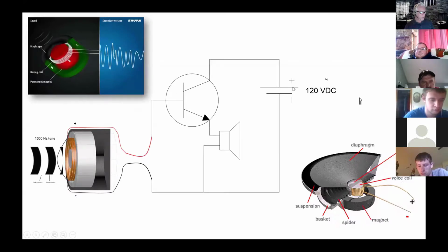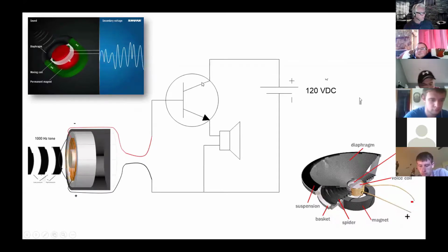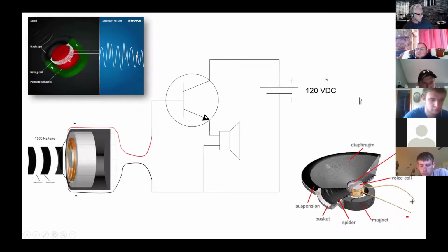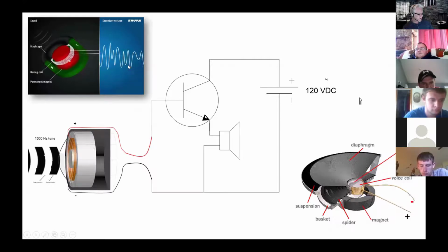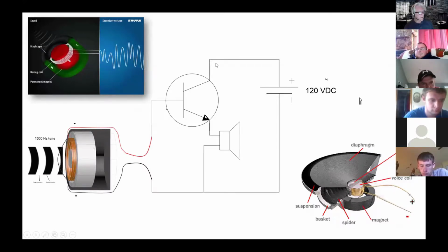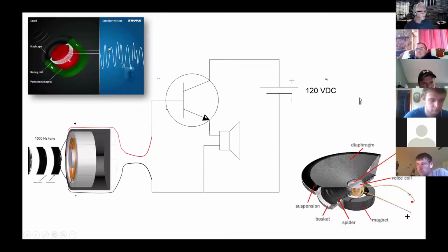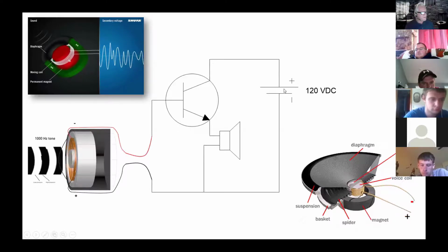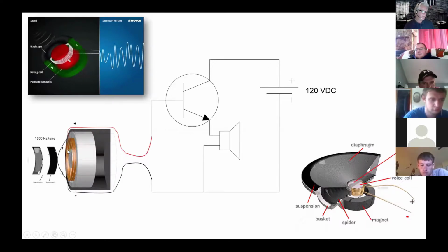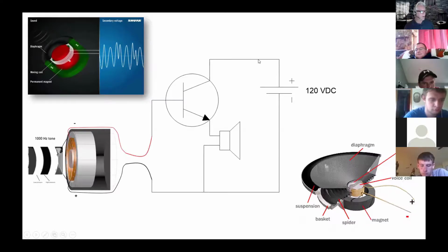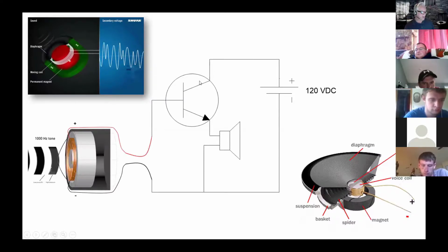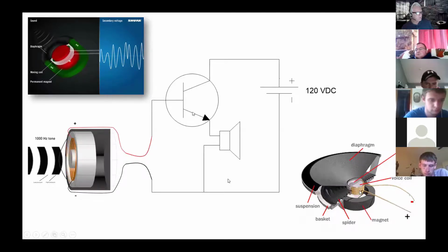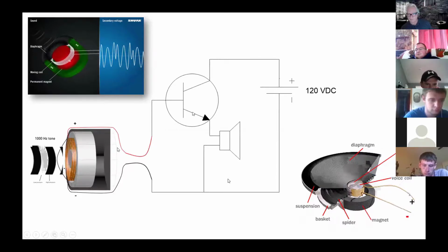I've got a power supply that pumps larger currents in here, and this varying signal that looks like this is opening this gate up correspondingly, and the collector emitter current follows this pattern, but at a much greater level of current. Now this can't supply this load, but this supply can. So now this supply delivers a large amount of current to this load, but it's being controlled by this small signal. That's how an amplifier works.